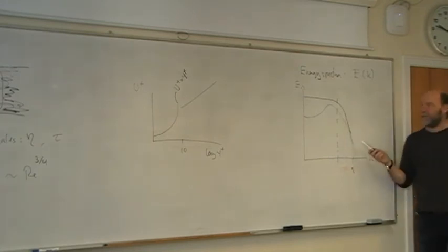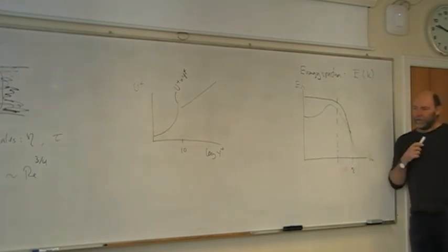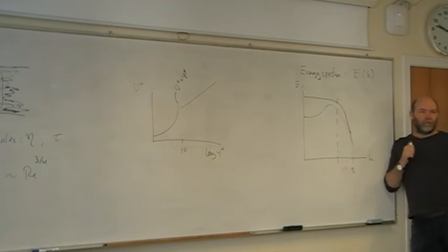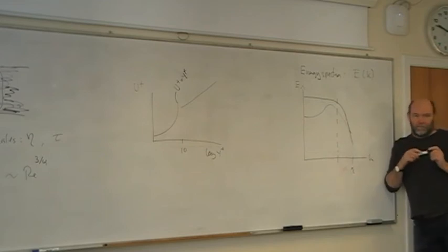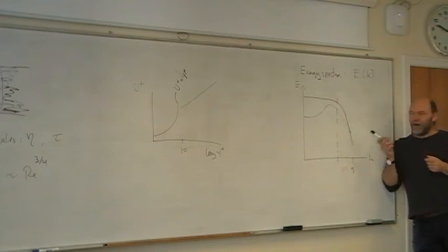You can't say that the energy spectra or the 2-point correlation can be a proof of anything. If they look okay, then at least you have a suspicion that maybe nothing is wrong. Then your simulation is okay. So it's sort of just to validate that it's not wrong. It may be right. Is it similar to residuals? If they look bad, then it's definitely bad. If they look good, it might be correct. Yeah. So you have to look elsewhere for evidence that your simulation is a-okay.